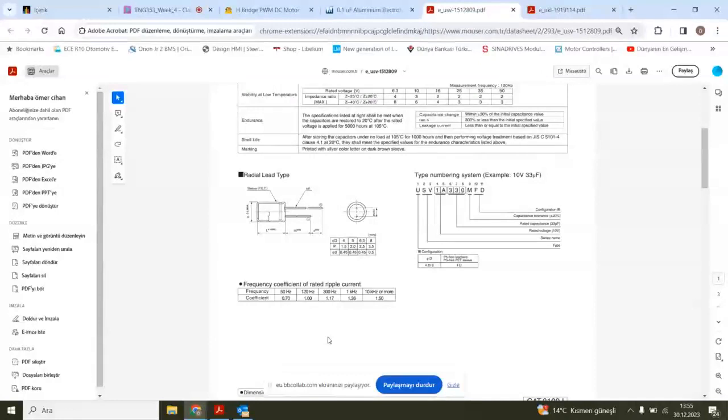You can select, please open your KiCad page. Last week, as students came to my office, we selected together. Parameter selection screen, probably you know in KiCad. You can write THT capacitor, and then if you click any one, you will see the dimension of the capacitor.